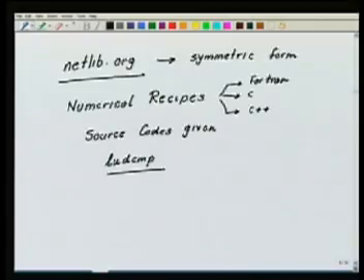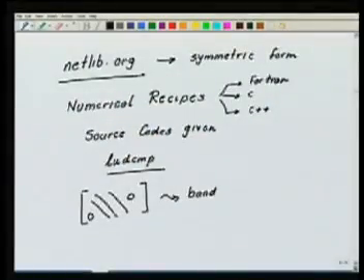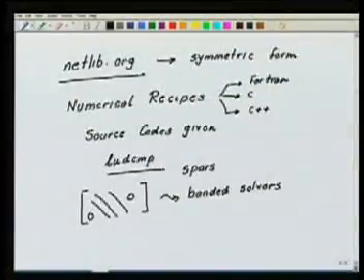Okay. So, once we have now obtained the solver, which is the Ldu decomposition based, certainly for us, we know our stiffness matrix is going to be banded in nature. That is, there is only going to be a certain number of elements on either side of the main diagonal which are going to be non-zero, everything else is 0. In that case, I can further reduce my cost of doing the elimination or finding the solution. So, you can find in these books the banded solvers. So, essentially what happens when you have this kind of a property, that your matrix is sparse, okay, that is there are a lot of zeros in the matrix, then I can simply store only the part which is non-zero.